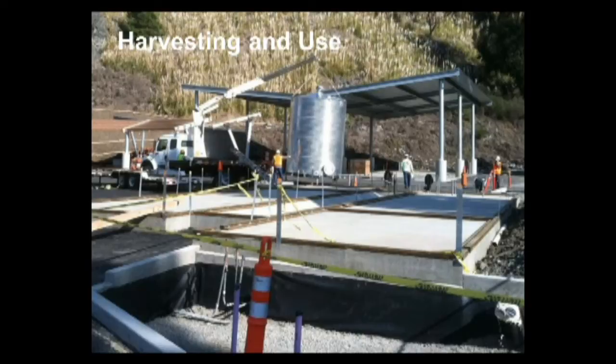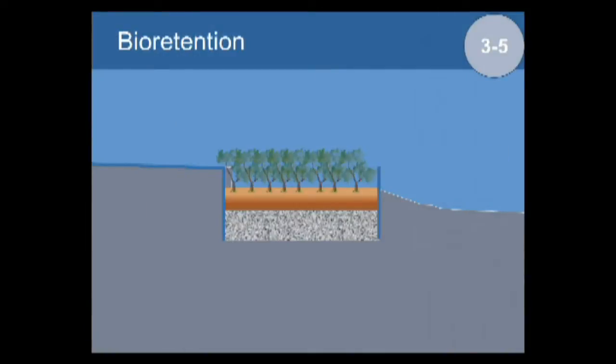But when it came to actually looking at the amount of water that you wanted to treat, they built a bioretention facility here downstream from it, which was sized the same way as any bioretention facility would have been sized. The reason is you've got to worry about the big storms, and the big storms come typically when that thing's already full. So you don't get a lot of benefit on the treatment side from diverting runoff for reuse. So the answer here is that we're generally in an urbanized area. We're talking about most of our impervious areas being directed to drain to bioretention facilities.